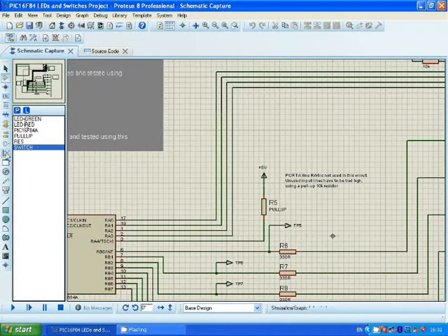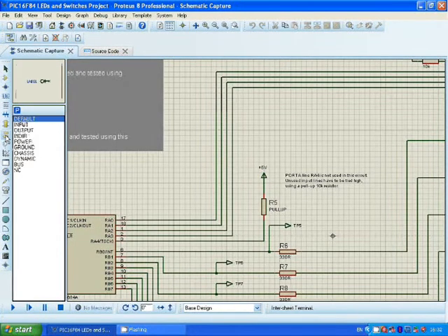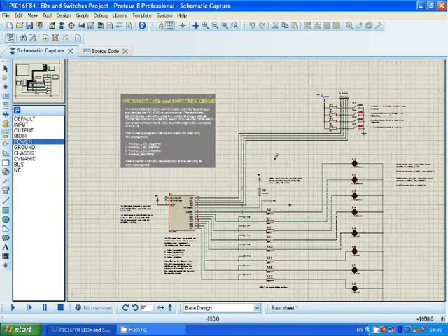Now to find those, you need to go over here. Here is ground, so you go in here to these terminals and you click on ground. So that's one symbol you have to put on your circuit, and the other one is right beside it, it's power. Now it's not labelled at the moment, and when you drag it over there, I'll want you to label it as plus 5 volts. So you have to put power and ground.